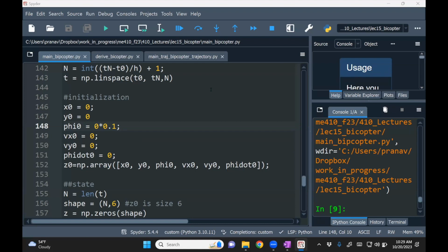And once you have that thrust, you can find a mapping between the thrust force and the propeller speed. And you have basically identified the thrust force. Once you know the thrust force, then it's a matter of taking the simulation and going with this, because all the simulation cares about is just the thrust force. Once you have a measure for the thrust force on the device, you have it. But there's no real thrust force on a device. It's only motors spinning fast, but the spinning generates an upward force.